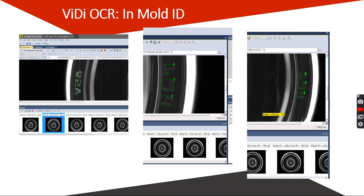Here's the first one. We're looking at the ViDi OCR or ViDi Read tool. There were actually 2 character sets that we were reading. We'll call it mold ID, that's the V28, and then core ID, which is really difficult to see, but it's actually a 1, a 9, and a 4. The customer asked us to deploy this, I think a year or 2 ago, with their standard rules-based tools, and because of the variability, the best we could do on the mold ID, the V28, was an 85% read rate. On this one here, it was much worse, 35%.